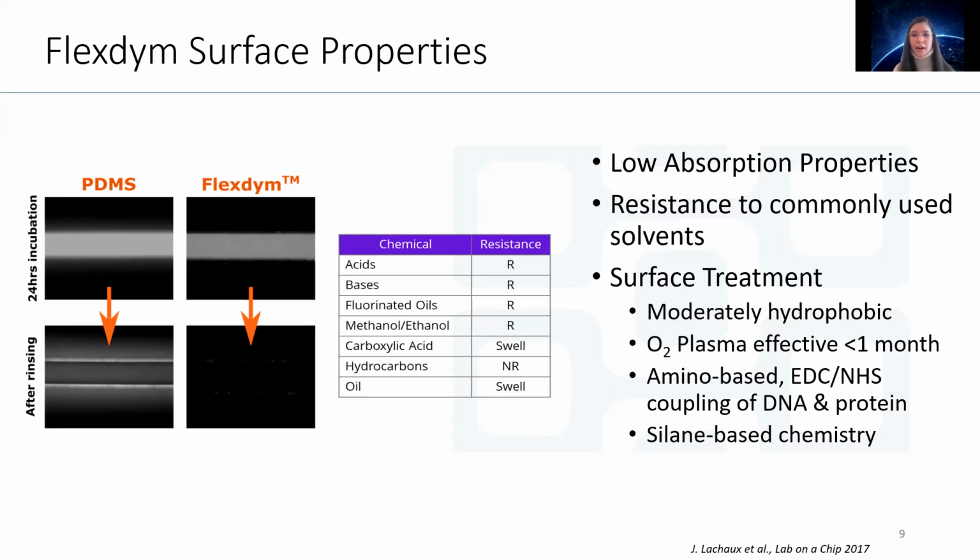But this result is completely avoided with the Flexdym because the Flexdym does not absorb the molecules in the same way as the PDMS. And not only that, the polymeric chains are not going to leach out into the media that is inside of the channel because of those styrenic blocks that act like anchors.